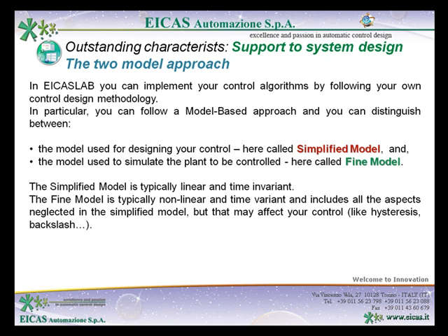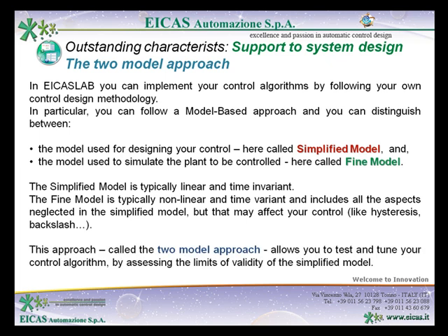includes all the aspects neglected in the simplified model, but that may act on the frequency band of the control and may affect your control, such as hysteresis and backlash. This approach, called the two-model approach, allows you to test and tune your control algorithm by assessing the limits of validity of the simplified model.